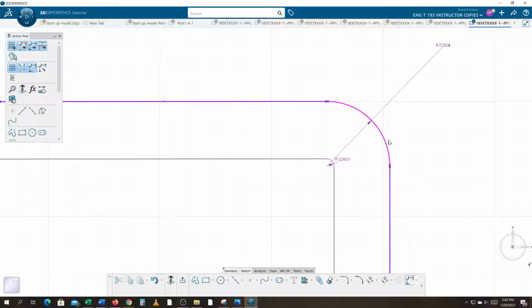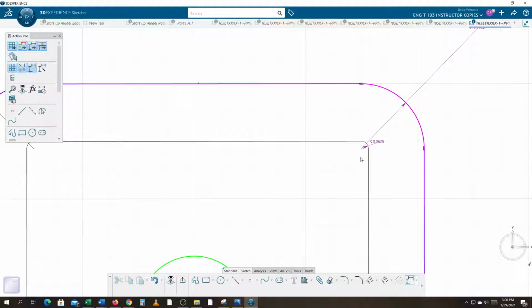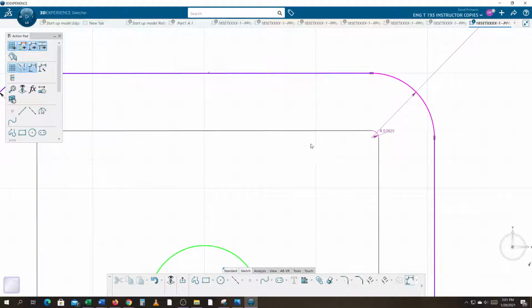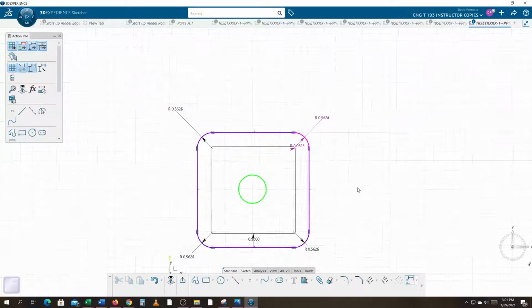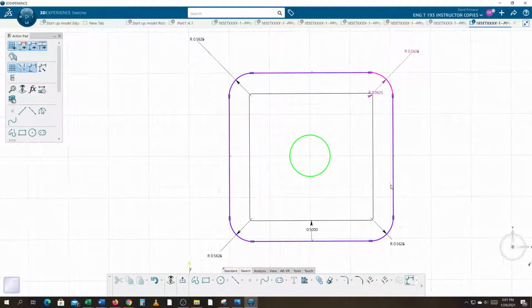So if I bump up the radius to 0.53, I'm still within engineering tolerance, and I can create a toolpath that I know is just going to wrap around. There'd only be like a 0.03 radius, but it's enough to hold tangency, so I'm not getting stuck at one point and doing a 90-degree angle, because it's going to almost pause for effect when it hits that point and continue to go to the next line. It's not a good machining practice. So when you're designing parts, try and bear that in mind.